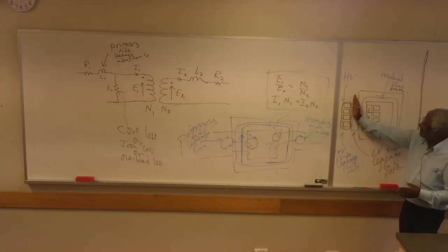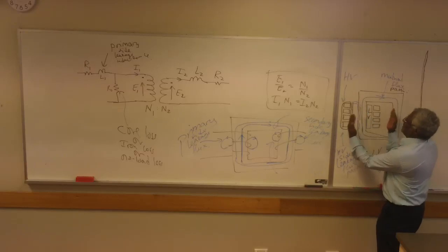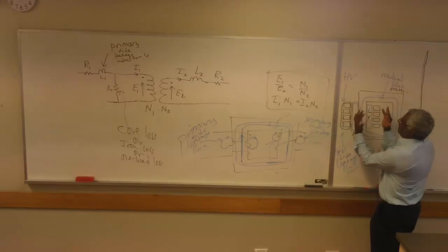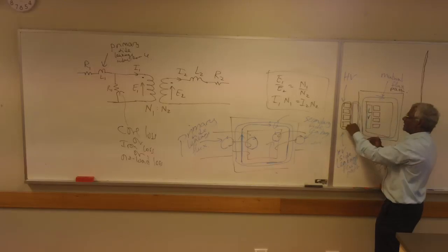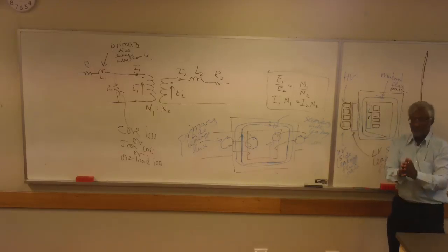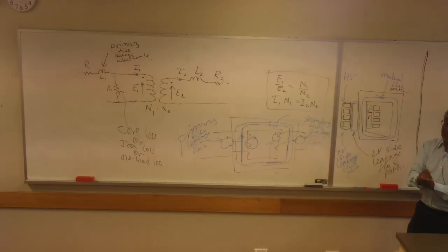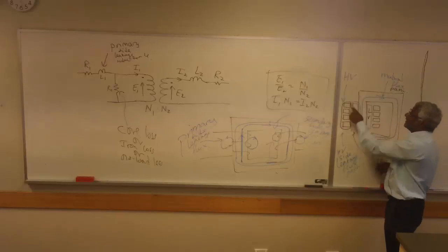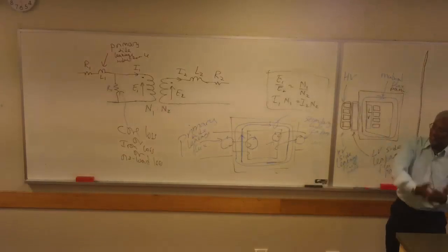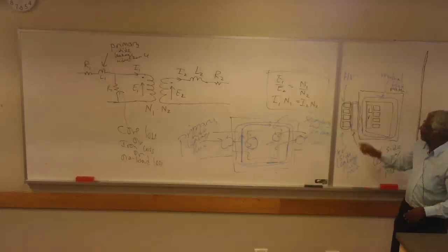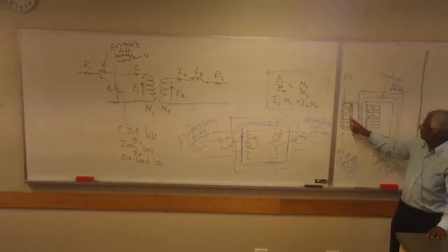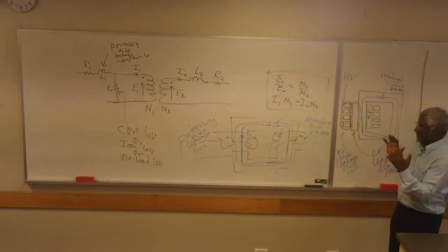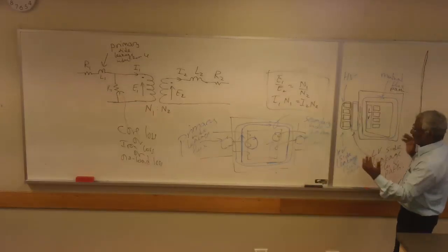That's right. So you increase this gap here. You would make the HV more separate from the LV, have more gap here, and that would give you more leakage if you wanted it. On the other hand, you do have situations where this gap would be big anyway, giving you probably more leakage than what you want. And why would that gap be quite big? This gap here in between the LV and the HV, why would that gap have to be made big?